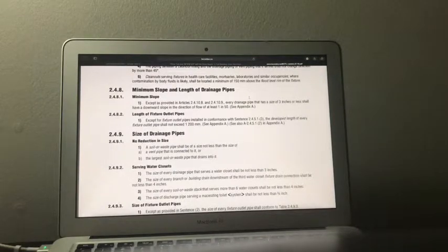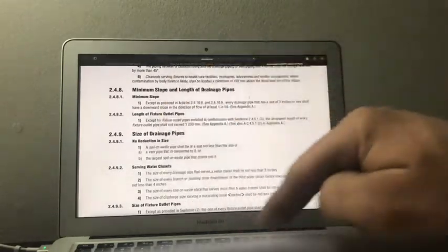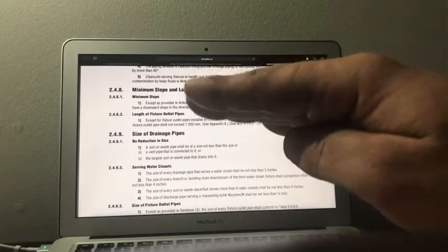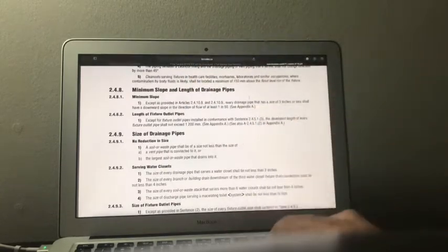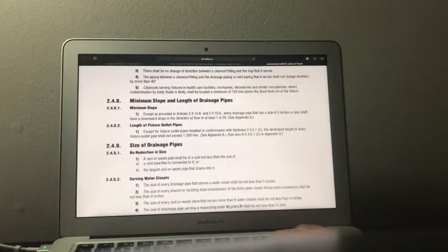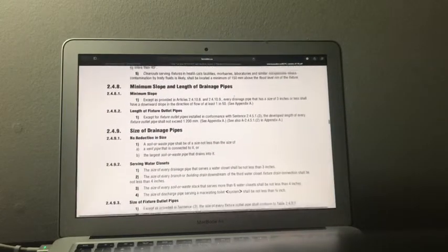I guess you could argue with an inspector and put it even lower. On this high efficiency washing machine, it uses half the water and the flood level rim is halfway through the circle of the glass. So I'm going to put my T at, let's say, 26 inches. Maybe if you want to argue the lowest flood level rim, you could do that. And so that's kind of which heights we're talking about for flood level rim there.